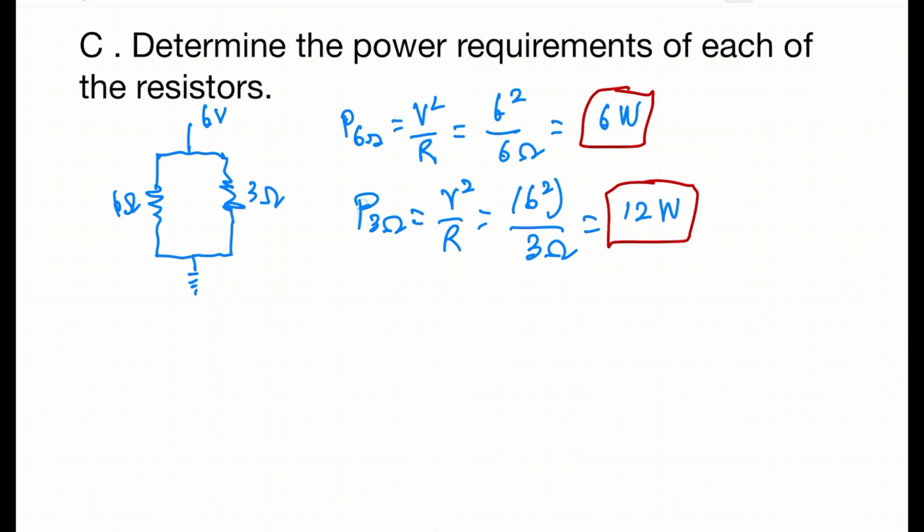Okay, so now let's do a little double checking on this whole thing. What we want to do is check and make sure the power of the supply is equal to the power of the load, because that energy has to go somewhere. And we have to make sure that they're the same. We know the power delivered by the supply was 36 watts, we calculated that. Now we've got the 3 resistors where the power is absorbed by the load, mostly converted into heat.